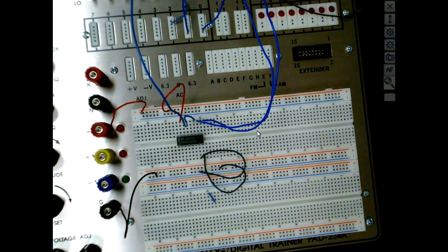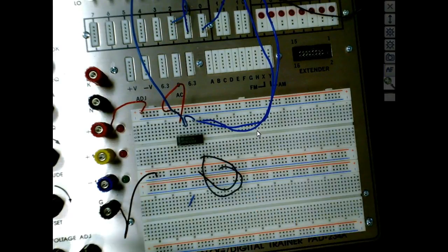E on our schematic, but I don't know exactly what it's labeled on the pinout. Strobe, right? So I told y'all these enable pins can be called different things. They can be called strobe, gate, chip select, or enable. So the schematic calls it E, but the data sheet we're looking at calls it strobe. And that's pin 7. Okay, and then the ground is hooked up. We got that.